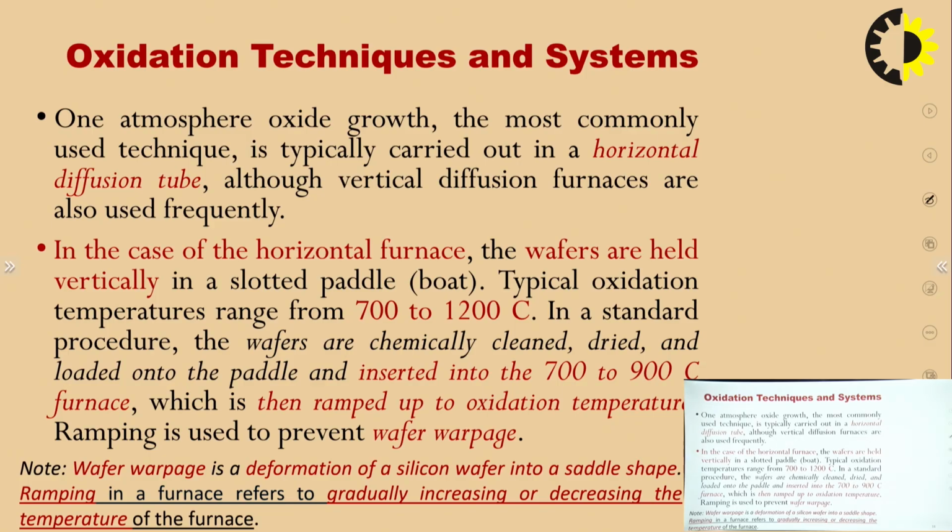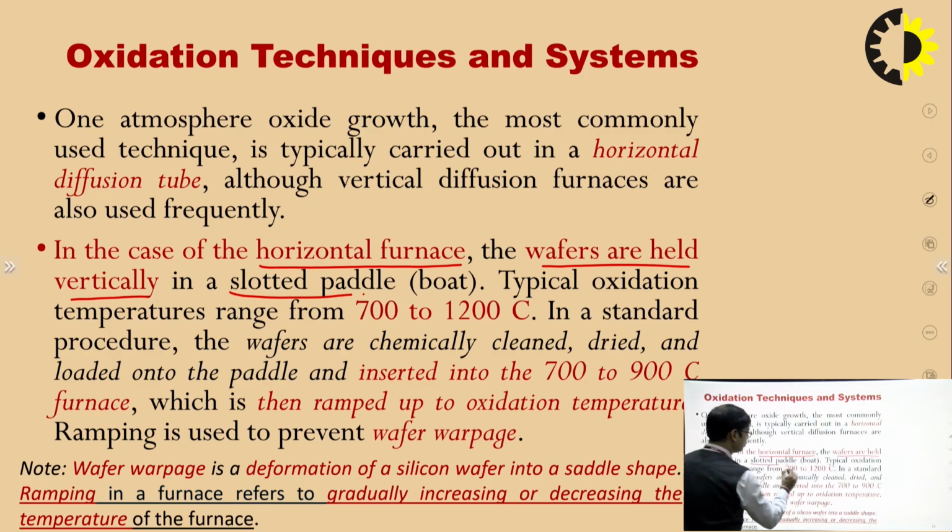Okay. Now, a typical oxidation system contains a horizontal furnace in which the wafers are held vertically in a slotted paddle, also known as a boat.